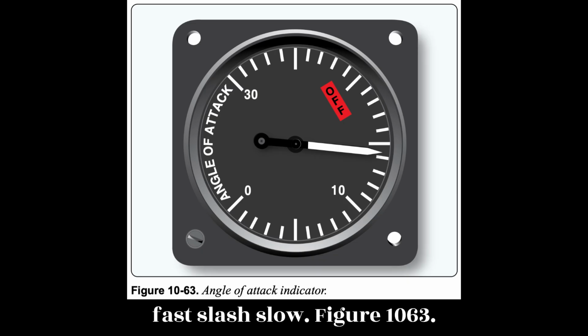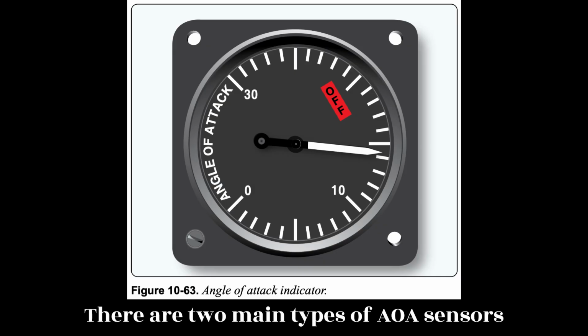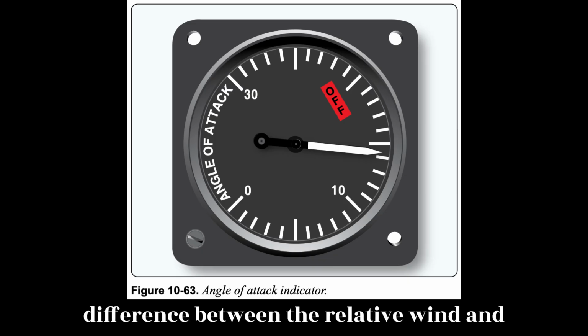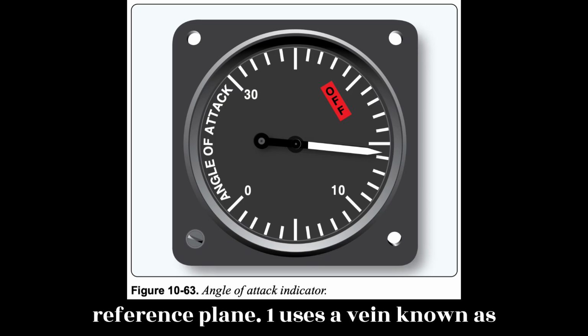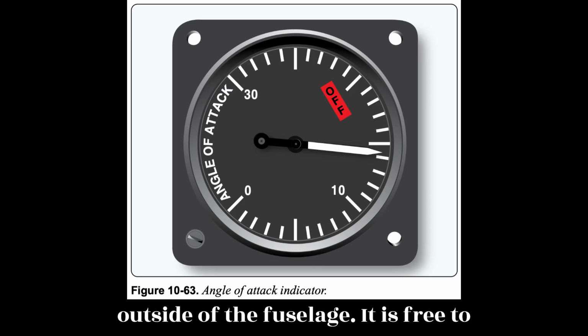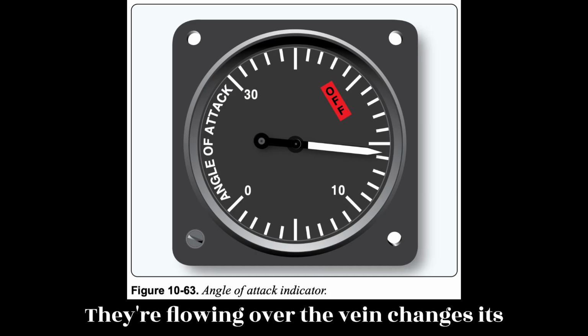Figure 10.63. There are two main types of AOA sensors in common use. Both detect the angular difference between the relative wind and the fuselage, which is used as a reference plane. One uses a vane, known as an alpha vane, externally mounted to the outside of the fuselage. It is free to rotate in the wind. As the AOA changes, air flowing over the vane changes its angle.